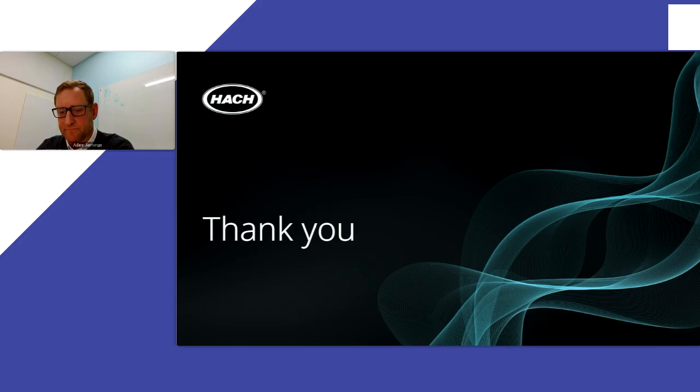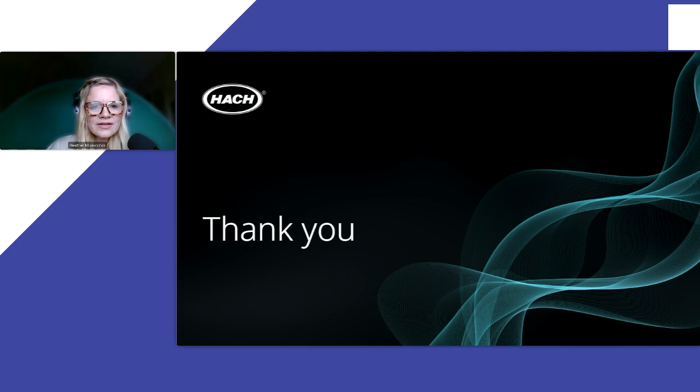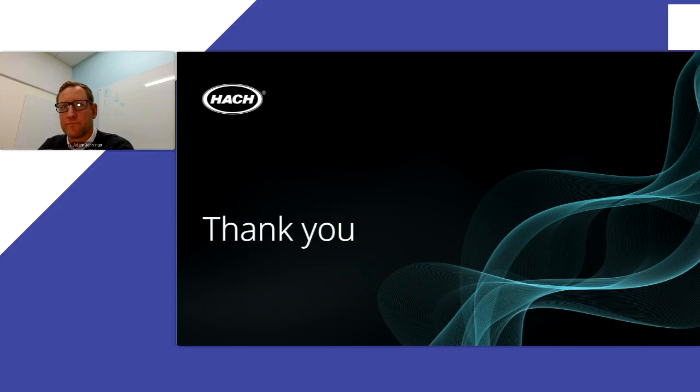Very good. Thank you so much. And moving on, this question is asking, what effect have you seen from low pH on nitrification? Let's say 6.7-ish. That's from Michelle. Yeah, great question. pH is an interesting measurement point, and we do it all the time in lots of different places, whether we're doing grab samples in a wastewater facility or measuring online with an online pH probe. And it's a really inexpensive way to get a pulse on